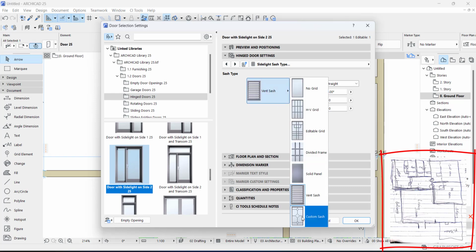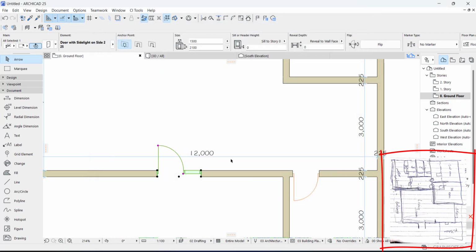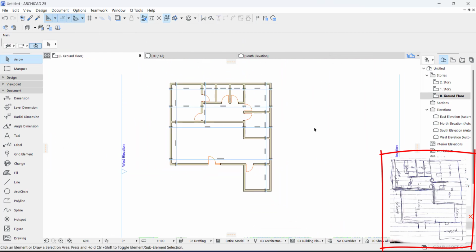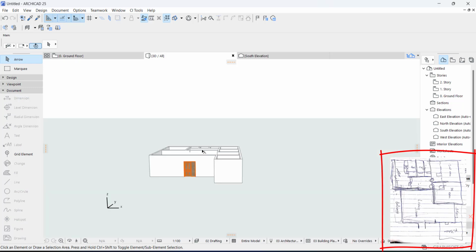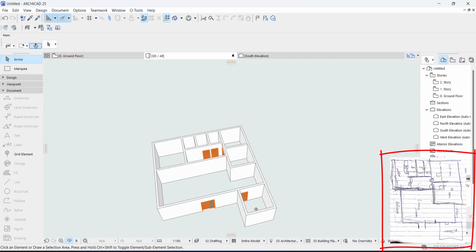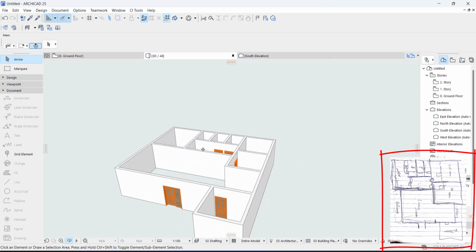This is custom. When you create yours, this is what you choose. But if all these are not what you want, you create yours. But I'm going to select this for the purpose of this lesson, and this is what we have. Now I'm going to go to the 3D to see what we actually have. What you can do is just press F3 on your keyboard. If your F function is disturbing it, you press Fn and F3 on your keyboard, or you deactivate your Fn so that you can just press F3 for it. So this is your space, I believe.